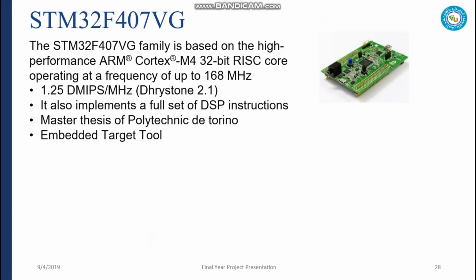Along with these things, this microcontroller has the corresponding embedded target tool provided by MATLAB. This means we don't have to program this microcontroller. We only have to use the embedded target tool to convert our Simulink diagram and burn it on the microcontroller.